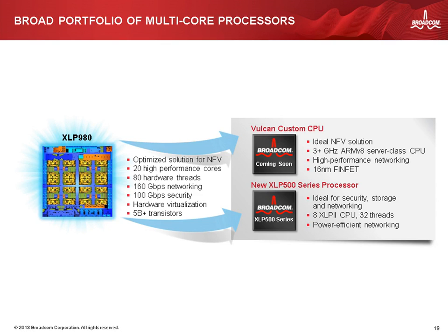So what we've done is we've developed a new class of multi-core SoC, and the family name is Vulkan, and it is a superscalar ARMv8 processor, and it has similar performance to the existing compute platforms. And it has up to 32 cores, which are four-way threaded, so 128 CPUs on board. And it's based on current technology, 16-nanometer FinFET technology.